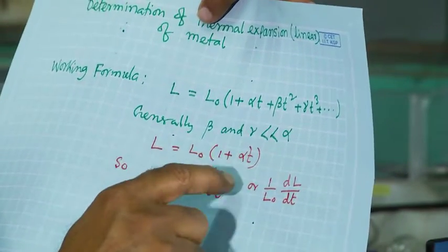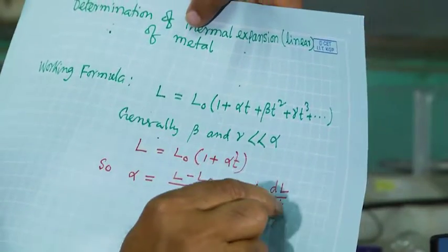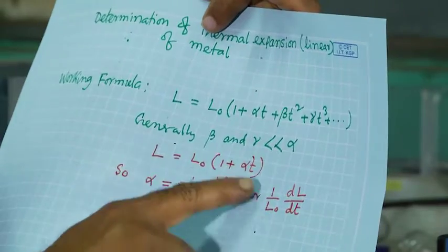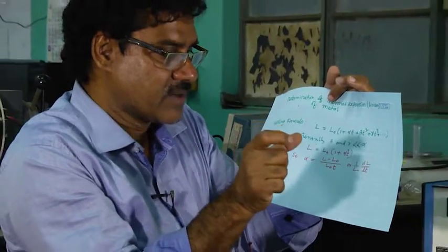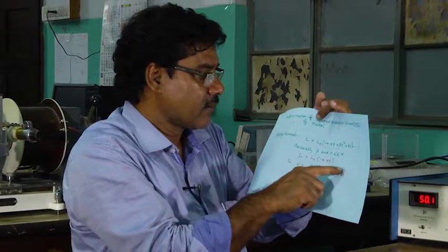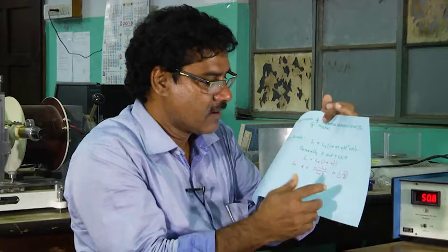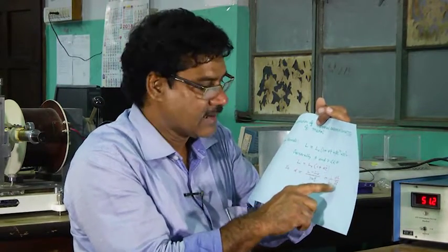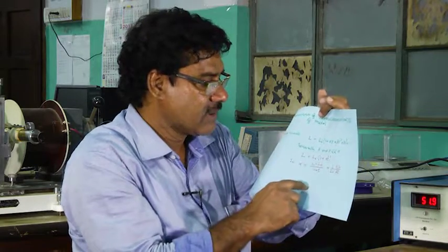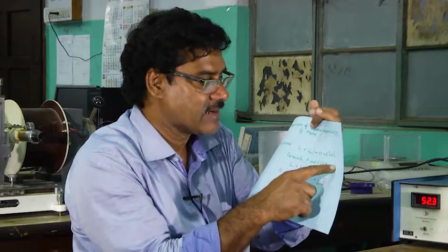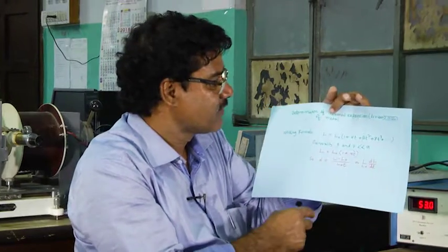Okay. So, one can write del L by del t times 1 by L0. Here we are getting this due to the temperature difference from the original one, of course, L0 corresponding to the temperature T0. So, for the temperature difference from the original, we are noting down the increment of the length. Now, you have data for temperature as well as for the expansion, delta T and delta L. So, you can plot a graph, you have 15 sets of data. Basically you will get a more or less linear curve. Initially it is linear, then because of the other parameters at higher temperature, it will curve.